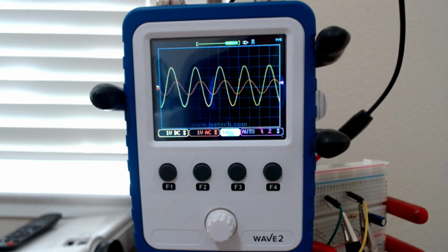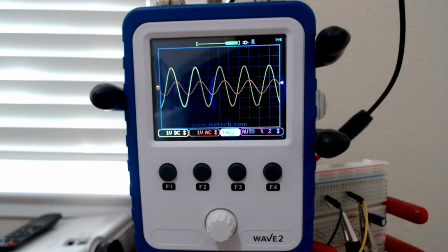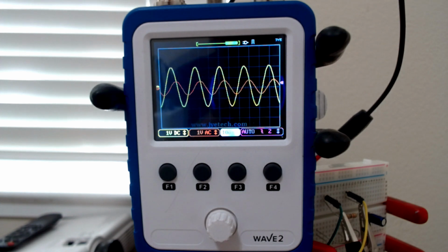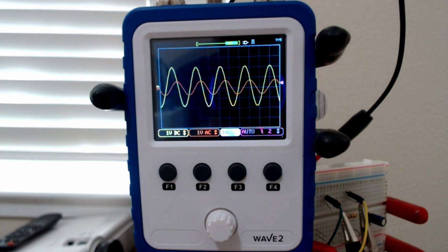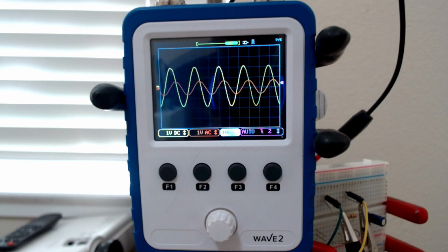In fact, if I had a resistor, a capacitor, and an inductor, the phase shift will go from minus 90 degrees to plus 90 degrees. So that's the range. It'll go from minus 90 to plus 90. So when the frequency is very high, then the phase shift will approach 90 degrees. Because if you remember, the equation I wrote for the phase shift was the inverse tangent of the reactance of the inductor divided by the resistance. And so the numerator has an omega in it.